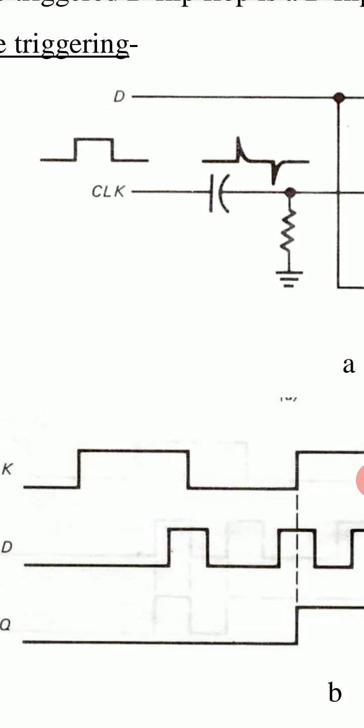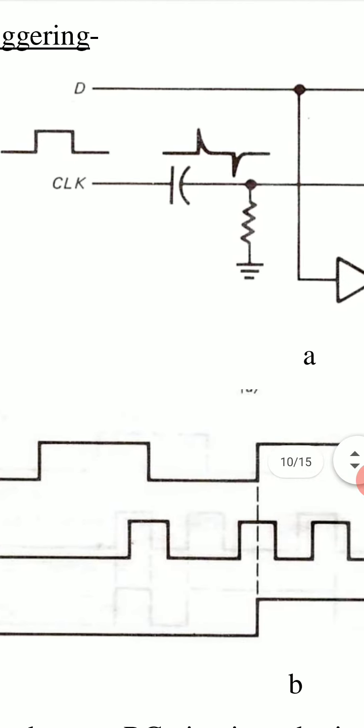And then we see that voltage across R will be like as shown in this figure. And similarly, when this clock signal goes from 1 to 0, that is falling edge or negative edge, then we also observe a sharp edge as shown in this figure for the voltage across the resistance. The diagram of voltage across the resistance of RC circuit is shown in this figure.